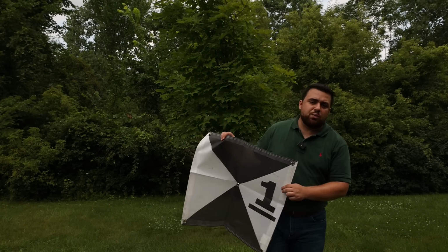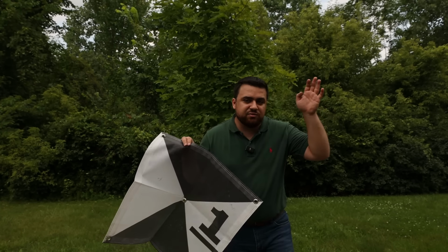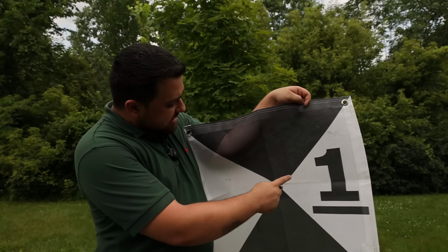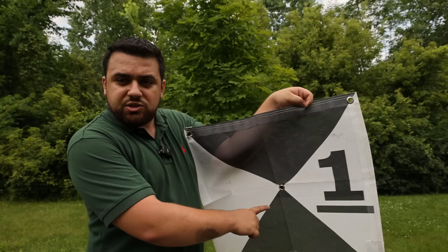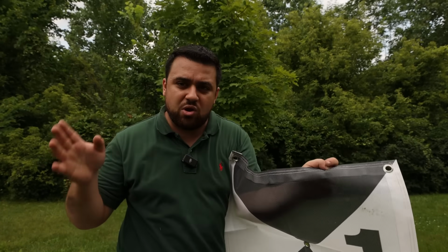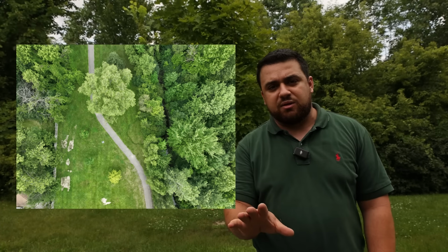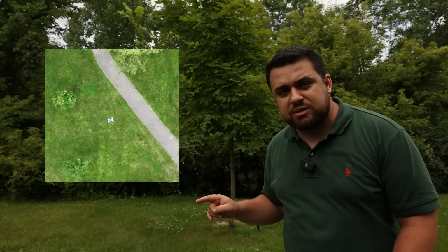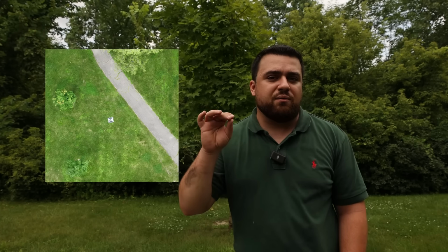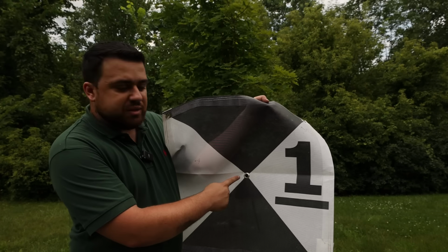Now, we'll go over georeferencing in the software at the end of this course, but basically what we're doing is identifying the center of this target in our photogrammetry software. So each image will show this target from an aerial perspective, and we will identify the survey coordinates of each of these targets by selecting the pixel of each image that corresponds with the center of the target. This, along with high accuracy geotags for our imagery, will give us the maximum level of accuracy necessary for drone surveying.